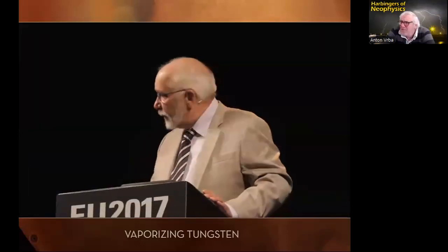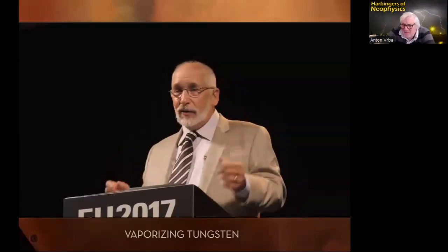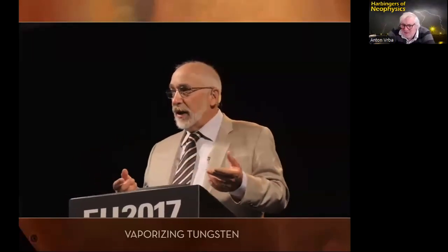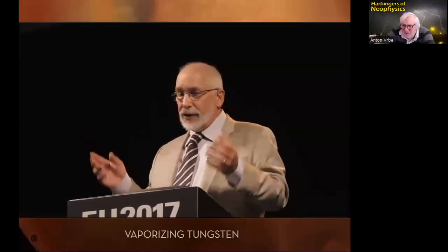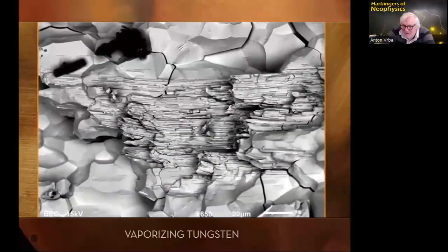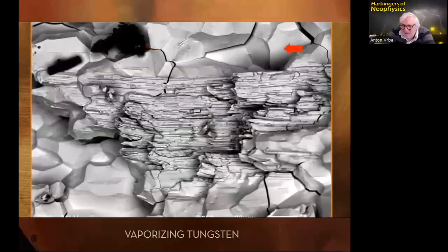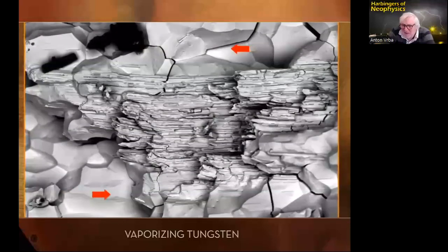So we decided, and this is when Paul got involved, he says, listen, I know some guys at the University of Toronto, let's get this thing in and get some scanning electron microscopy done. So we did. I'm going over the material in the tungsten. If you know anything about materials, what you're looking at here, the black stuff could be contamination, but the kind of geometrical shapes that you see above that other stuff that looks like shale is tungsten. It looks like it was getting melted.